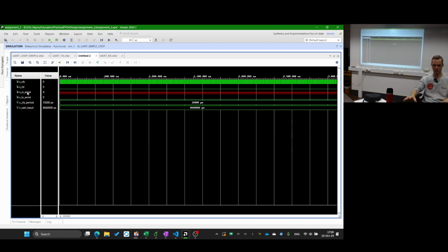So I've assigned, if you have seen it maybe, a signal to my RX channel. You can ask yourself if that's correct. So this leads to a collision because it's the wrong way around. So I collide one with another. It will lead to a collision when I put two signals together at the same time. That's also why you don't want to have in-outs, because it will also give you a warning and so on. In the design, you can technically not do it. It will not compile. But in a test bench, you can drive a wrong signal. That's possible, but it will end up in something like this.